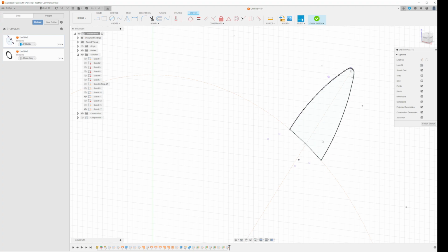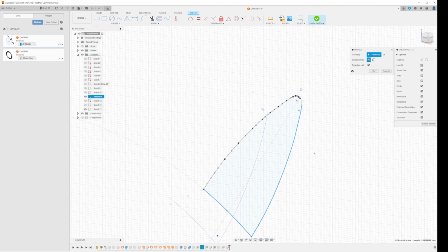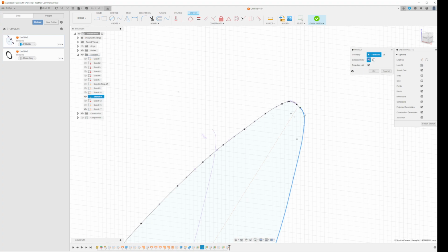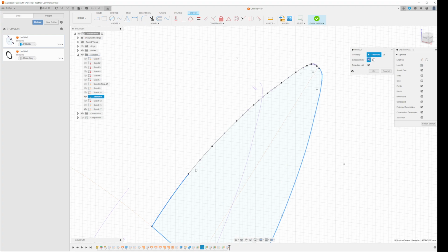And the easiest way to project is just press P, and then you can just double click. If you double click, it will select the nearest one that is sort of connected to the point. And you can see it's recreating the points here. If you double click, it doesn't do it properly. So I'll just double click from the start, P from project, double click, and you see now it also selected the bottom because it interacts with the same point.